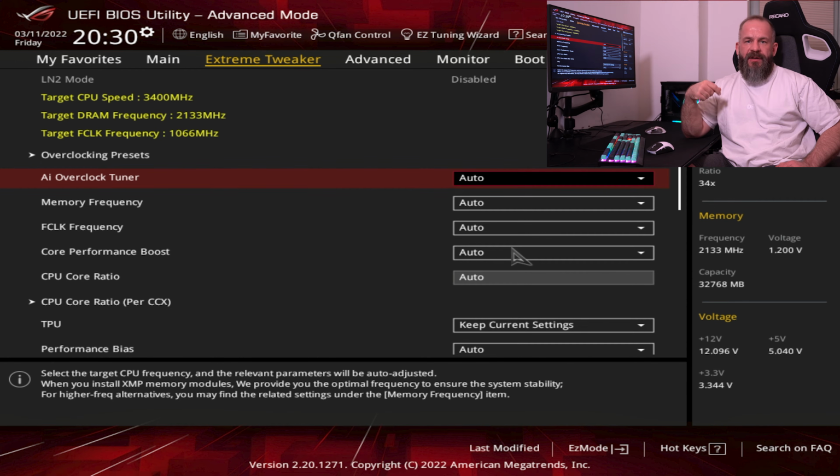But to be honest, I tried this a lot, I played this a lot, and I also used Hydra for a very long time, which is a great program, but basically for gaming it's insufficient because of the switching of the modes the whole time. That's why I decided to find a way to make a very good all-core overclocking with very awesome settings. So as I said, 1.465 volts right now, the core voltage, the clock is like it should, 100 megahertz, and we stay at 100 megahertz, guys, don't worry.